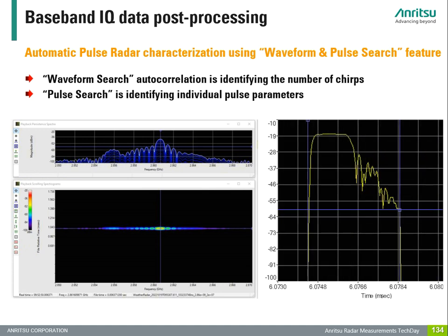Here we see the just mentioned extract. We have isolated a single pulse. You can observe the results in parallel in RTSA overlay, spectrogram, and power versus time. This part of the signal is now exported and used for autocorrelation measurements. The result will inform you how often exactly this signal occurred in the overall time record.